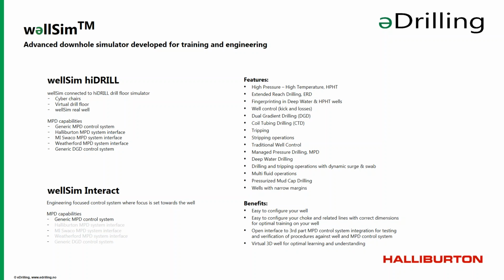It's also easy to configure the real choke and the flow lines as you are going to use offshore. That gives you the possibility to get proper pressures on the surface lines and make it really realistic. Combined with the MPD provider's control system, you're able to train the drilling crew together with the MPD provider crew on the real well together.